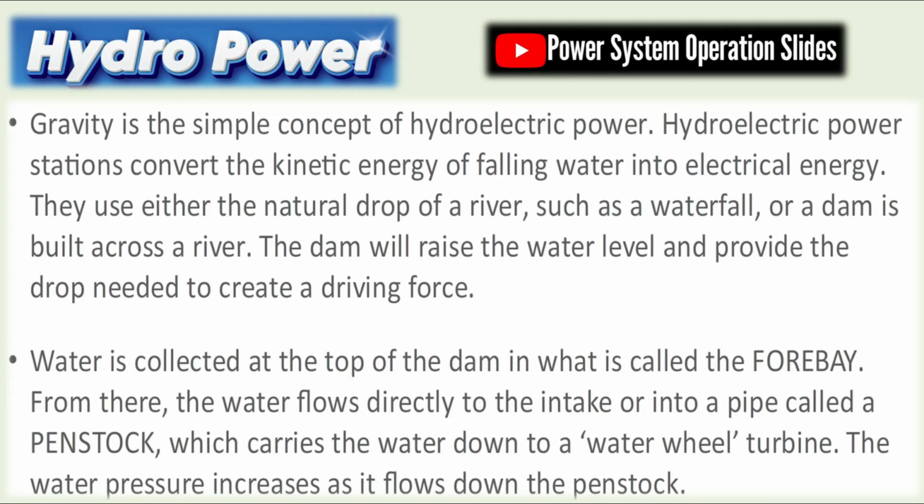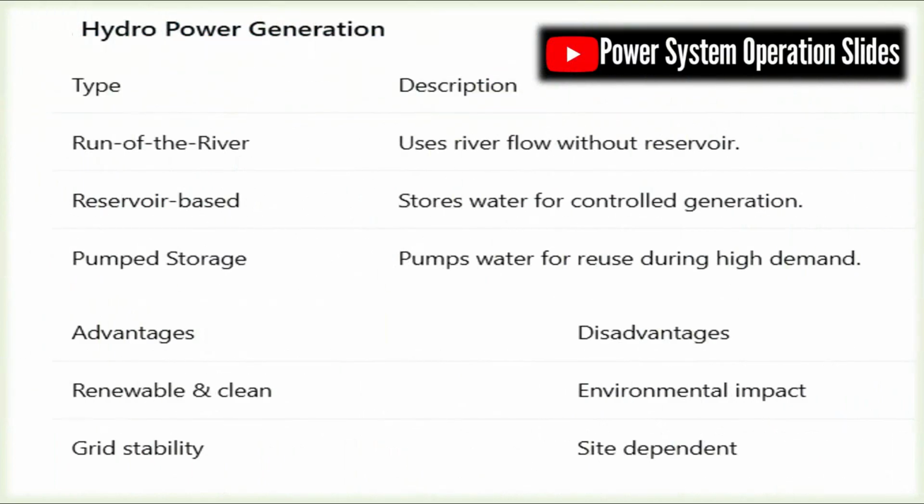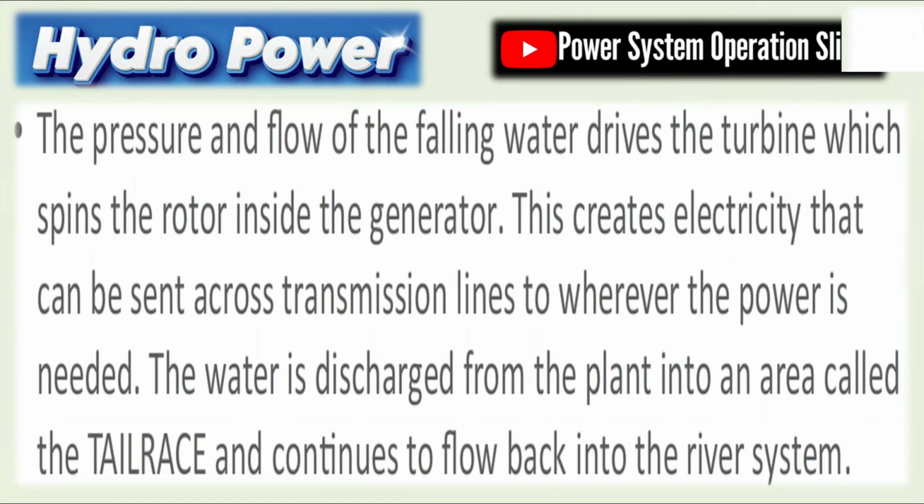Gas turbines operate on the Brayton cycle. They are compact, capable of fast startup, and widely used in peaking plants and aircraft. In power generation, they are often combined with steam turbines in CCGT configurations for enhanced efficiency.